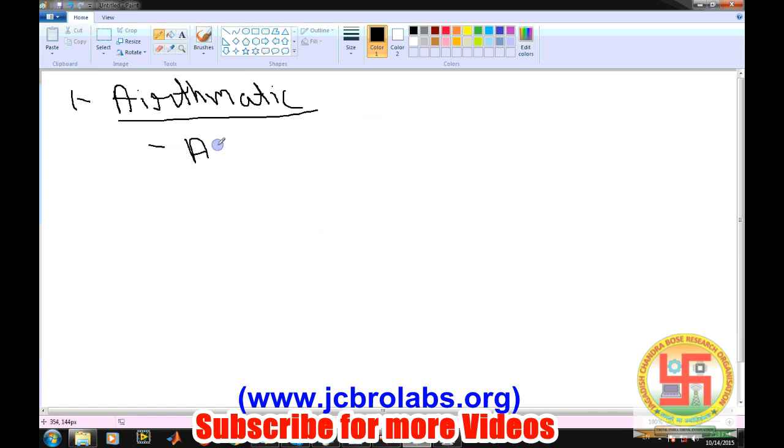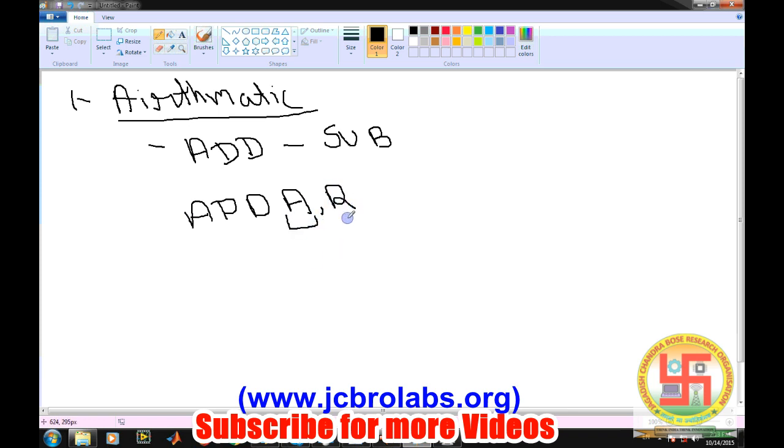If we talk about arithmetic operations, we have add, subtract. Say we have ADD A comma register. Its first operand needs to be the accumulator, and the second operand could be any register. Similarly, the SUBB command is there to subtract. In the subtract command, the first operand needs to be the accumulator, and the second operand could be any other register as well.